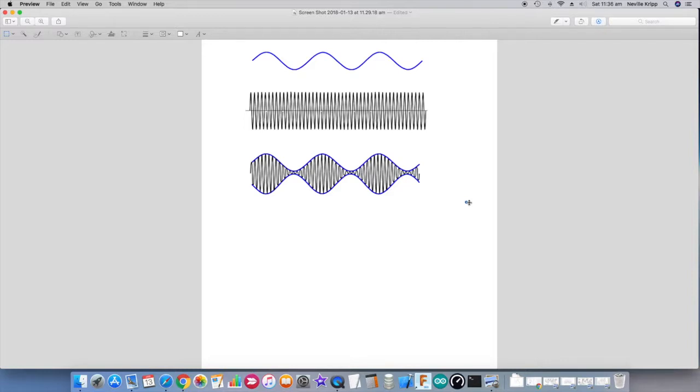So how can we actually recover that initial audio signal from that particular signal there? Now, we've already talked about the RF stage, the mixing stage, and the IF stage. The good thing about the superheterodyne receiver or technique is that RF signal with this modulated waveform on it, when it passes through the mixer, the IF signal, that is at 455 kilocycles, also still has that particular amplitude modulated signal on it.